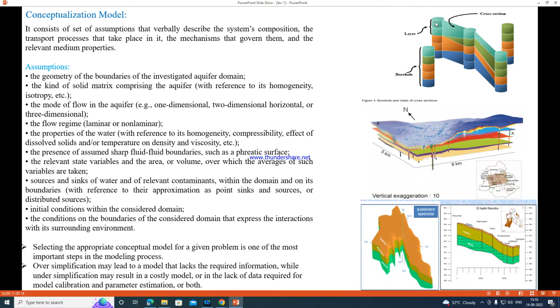Suppose this is the same type of sand layer; assume that it is sand and orangish clay. You know the top elevation, and you know up to what depth the sand is present, and up to what depth the clay is present. You can develop the elevation of each layer by subtracting the depths from the top elevation.